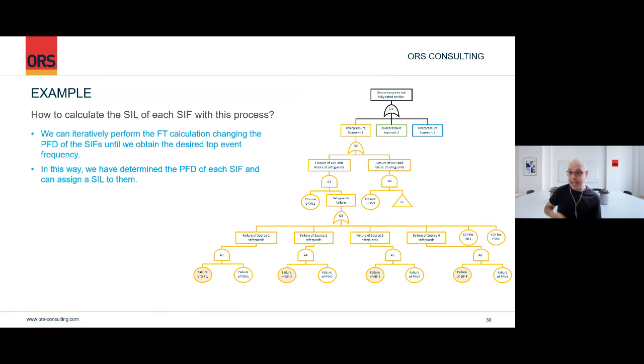So that is the way that you would find the required SIL for each of these functions at the same time. You cannot do this with LOPA because LOPA will only let you do one path. LOPA will not allow you doing the 4 paths and the common causes at the same time. I think maybe you could do it, but it's going to take you a lot longer to develop that worksheet than doing it with a fault tree. So for this type of scenario, for this type of event, this is much more simple. This is a much better approach.